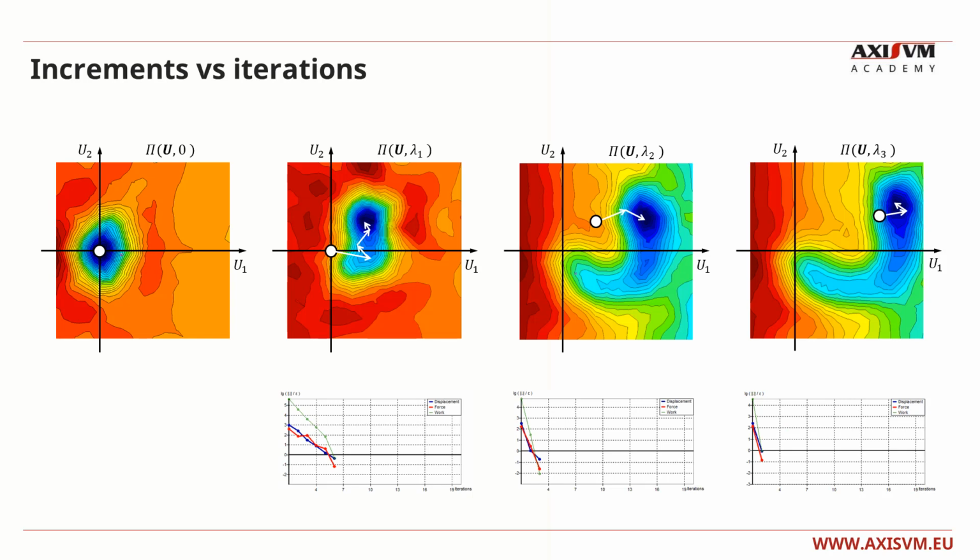Inserting sub-increments, the solver has to take shorter distances between the subsequent solution points. Starting the iteration process of the actual increment from the solution point of the previous one helps to avoid the hard territories of the map. It provides strong monotonic and fast convergence with a few iterations. We can say that it is usually not worse to use more increments, because the total number of iterations during the whole calculation can be lower than in case of just a few increments.